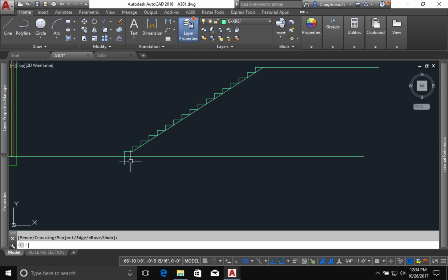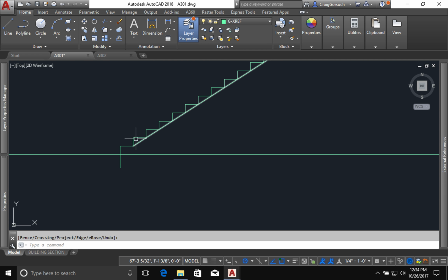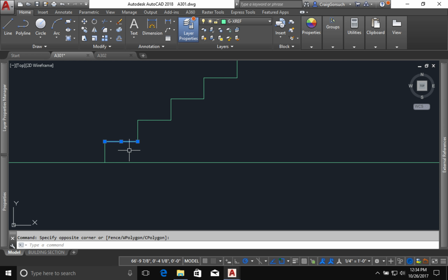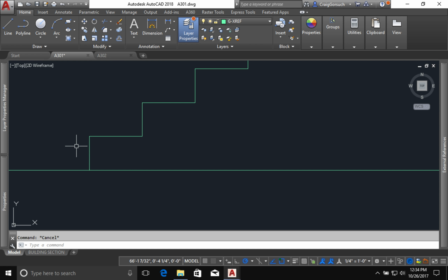There we go. So this is the most basic profile shape for your stairs that can exist. This accurately maps out the length of the tread, which is going to be the length of these little horizontal lines, and it also accurately dimensions out the height of all the vertical lines, and that dimension is roughly 7 1/16. It's actually a little different than that.